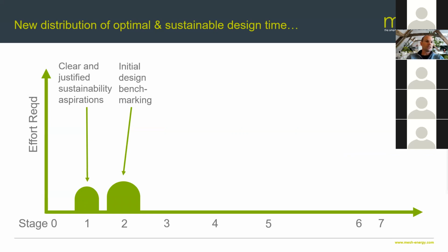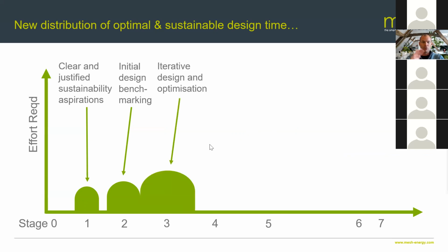If you're following RIBA 2025 or RIBA 2020 or RIBA 2030 or BREEAM or whatever it is, benchmark the design at that very early stage against those frameworks to see where you're at. Avoids any early surprises and may allow you to adjust. And remember, this is all before planning and doesn't have to cost a small fortune to do. Once you get that feedback, you iterate and optimize the design and start doing some initial high level M&E design work.